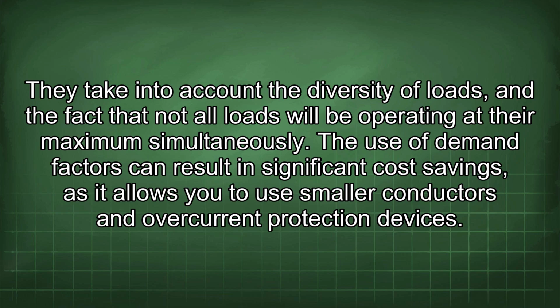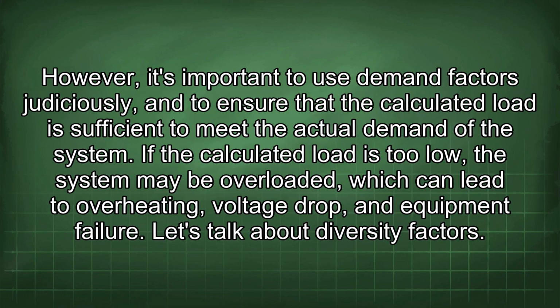They take into account the diversity of loads and the fact that not all loads will be operating at their maximum simultaneously. The use of demand factors can result in significant cost savings, as it allows you to use smaller conductors and overcurrent protection devices. However, it's important to use demand factors judiciously and to ensure that the calculated load is sufficient to meet the actual demand of the system. If the calculated load is too low, the system may be overloaded, which can lead to overheating, voltage drop, and equipment failure.